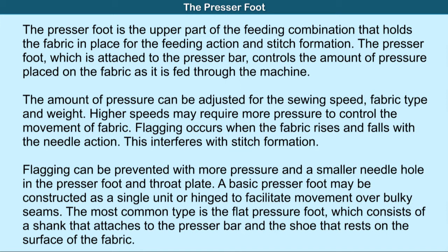The amount of pressure can be adjusted for the sewing speed and fabric type and weight. Higher speeds may require more pressure to control the movement of fabric.